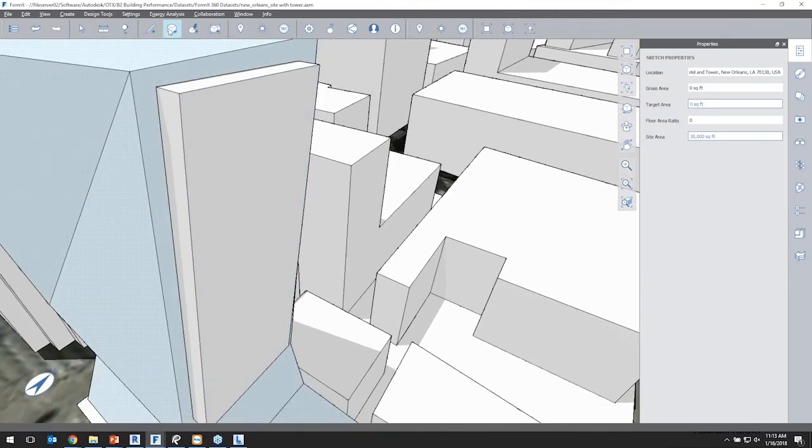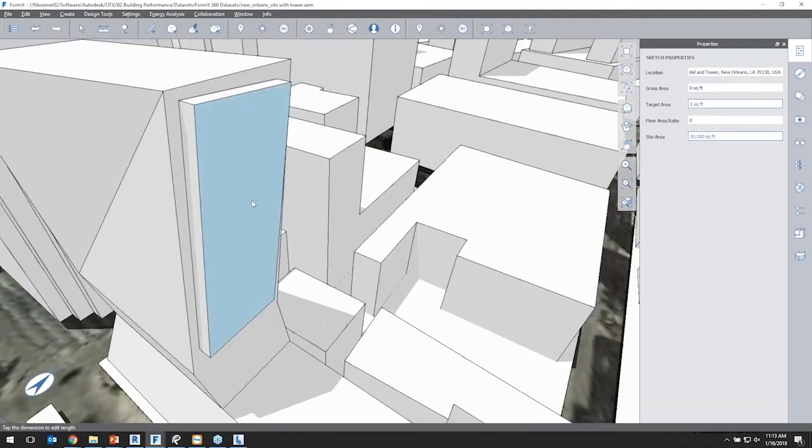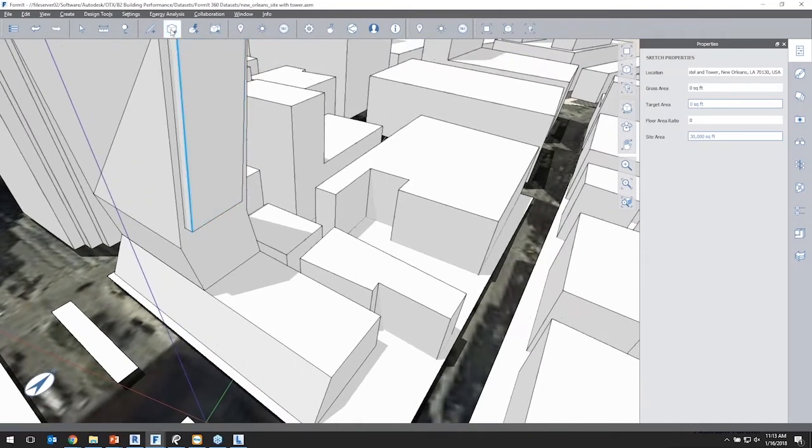My idea is not to do something as simple as that, but to play around with a couple of different pieces of geometry that we can illustrate how Format has tools for basic modeling and advanced modeling, meaning that I could draw geometry to extrude, to join, to subtract, to sweep, to cover and close things up. This is great for taking surfaces that are not closed and uniform and capping them and making sure that it ends up being a solid.